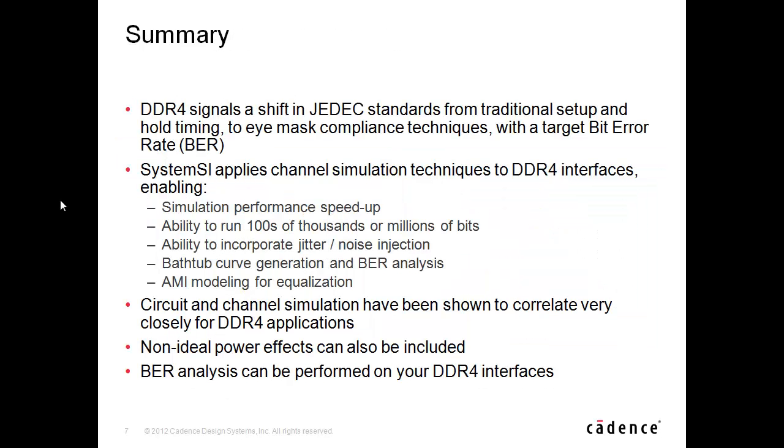DDR4 signals a shift in JEDEC standards from traditional setup and hold timing to eye mask compliance techniques, with the idea of a target bit error rate, or BER. Cadence's SystemSI addresses these challenges by applying channel simulation techniques previously used in serial link applications to DDR4 interfaces. This provides a huge simulation performance speedup and the ability to run hundreds of thousands or even millions of bits.